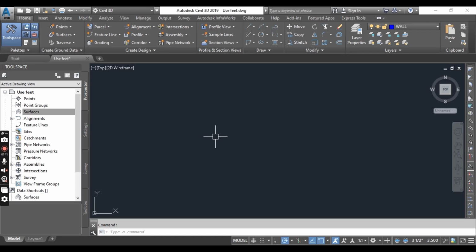There will be no specific layer defined since all of them will be set to layer 0. So any Civil 3D object you create in this drawing will be placed by default in that layer. Now we will learn in this section about features that allow you to import the settings and styles from a template, taking away all of the hassle of redefining the data of every drawing in Civil 3D. So it's the best practice for receiving a non-Civil 3D drawing.